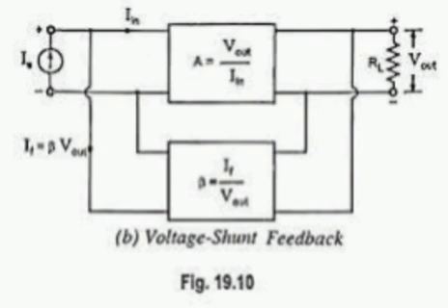Harmonic distortion. The harmonic distortion means the presence of frequency components in the waveform which are not present in the input signal. IC equal to B0 plus B1 into cos omega t plus B2 into cos 2 omega t plus and so on, Bn cos n omega t.